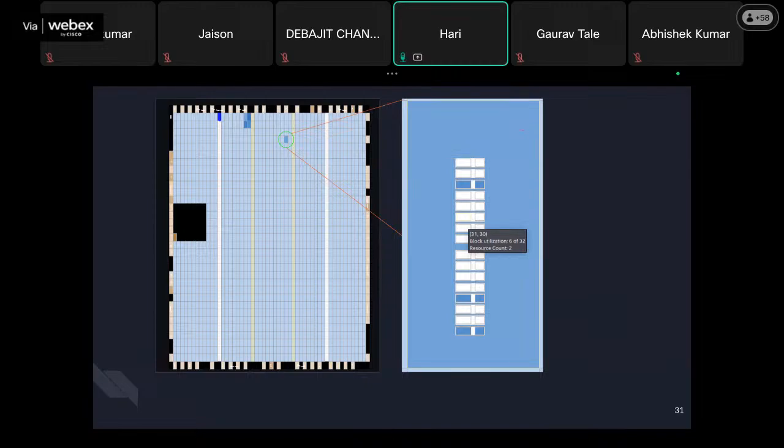So this is nothing but a chip planner. This particular diagram is from chip planner. Chip planner is nothing but your entire FPGA, basically an entire FPGA block, and you have a lot of logic elements, right? You have those small elements. Each FPGA has a defined amount of logic elements. Example, the DE0 Nano has 22,320 logic elements. Any FPGA will have a defined amount of logic elements.